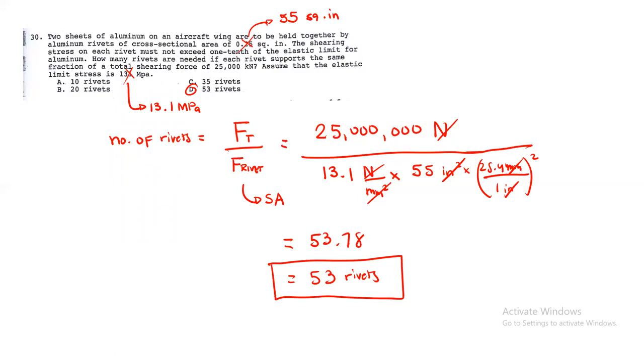So next, 31. A copper column of annular cross-section has an outer diameter and is subjected to an axial loading of 200. The allowable compressive stress is 14.4. We need to find the wall thickness. So how do we solve 31? Stress is equal to force over area. So a simple formula lang ang gagamitin dyan. Then the area is pi over 4 times (dO squared minus di squared).